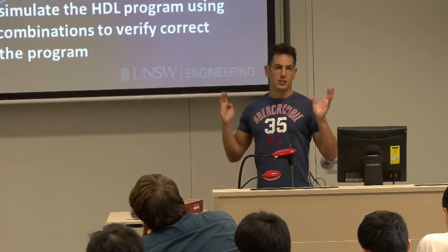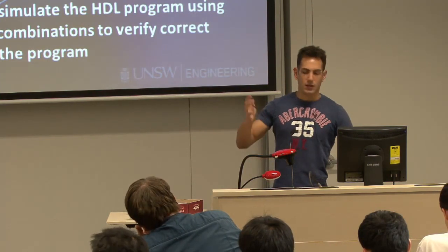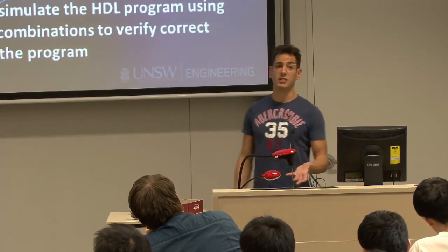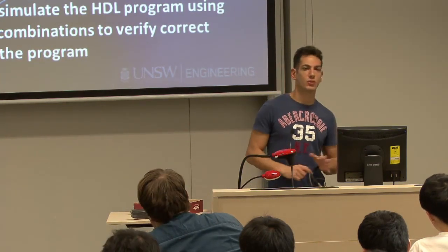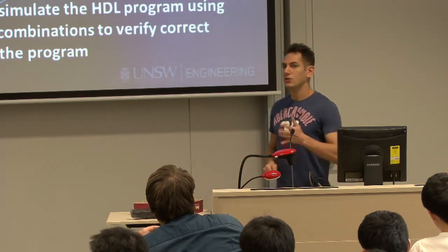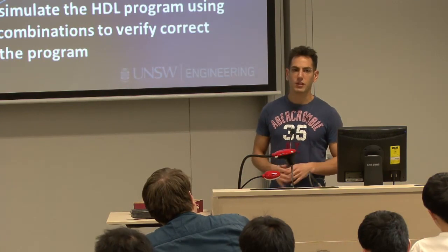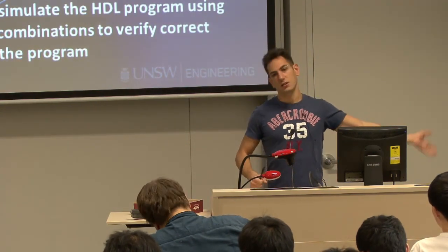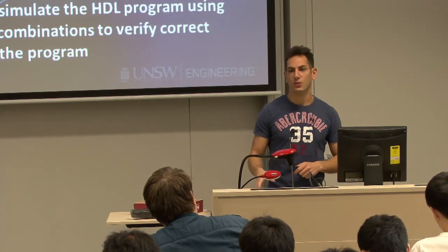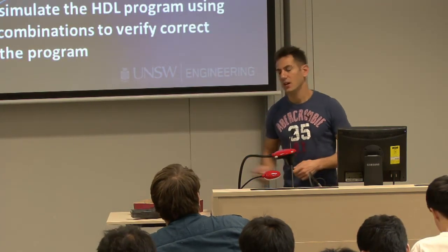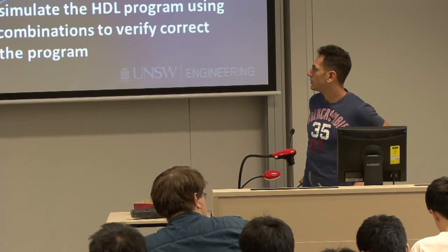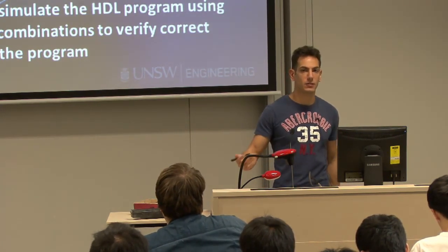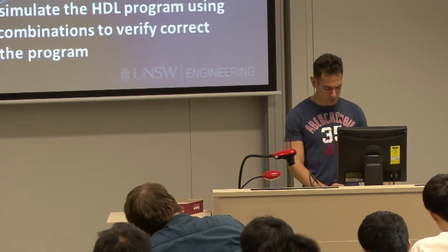Now, the last thing, which is a really important part of design tools, is the simulator. Before you actually go and implement things, you want to simulate to see that it does what you want. It's okay with FPGAs because you download it. If something doesn't work, that's all right. Not so great when you design an actual chip that you send to the manufacturers. It takes about a year to get your chip back, and then you go, oops. So you have to do some really heavy simulations and testing before you actually send it out for production.